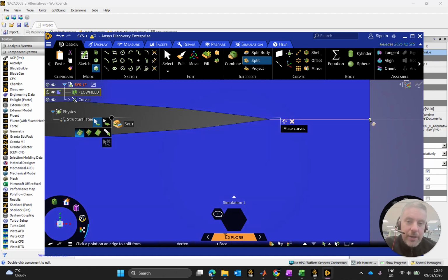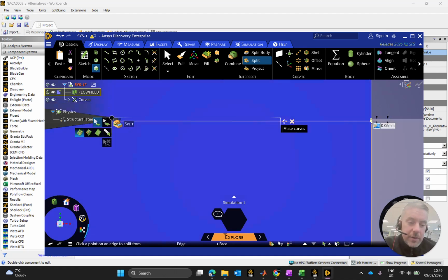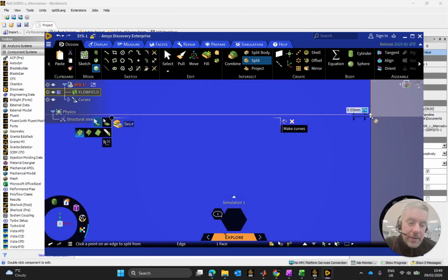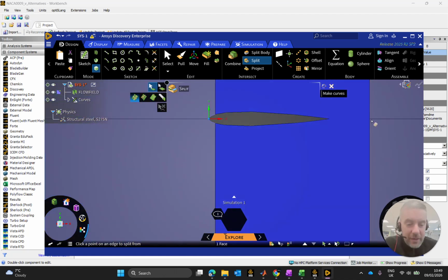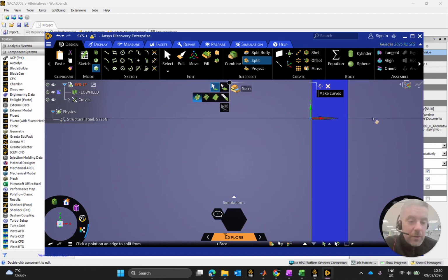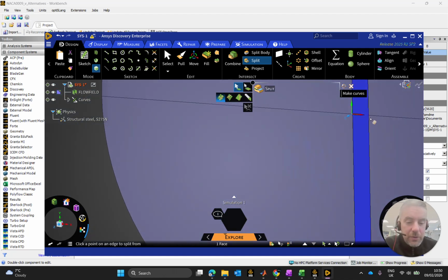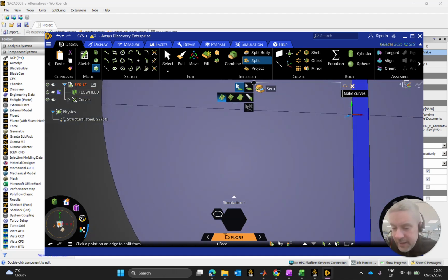But when you close the trailing edge, because we're dealing with a spline to close this, it mightn't necessarily be the case. If you do click it from the trailing edge here, there's no guarantee that you are actually going to land it straight into that point there. But if you click it here, it will land you fairly well into a good enough spot on your trailing edge. Now, what you could also do, indeed, is just join